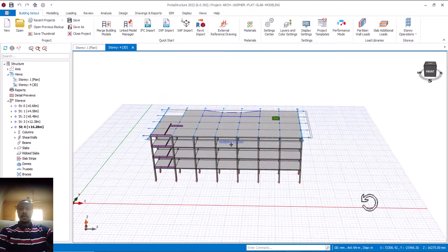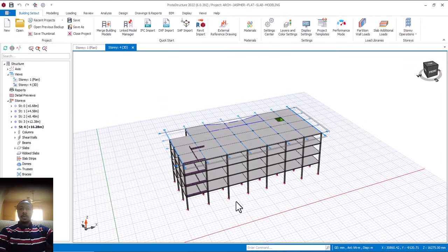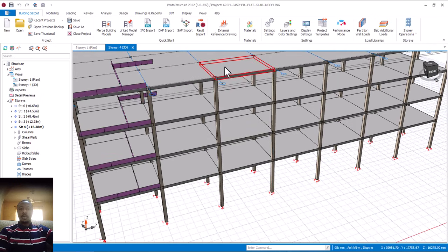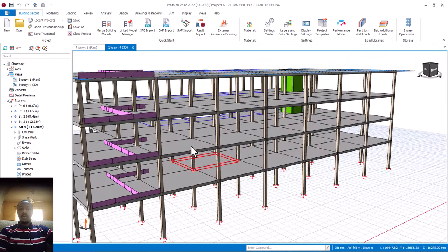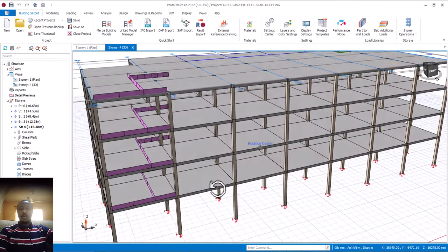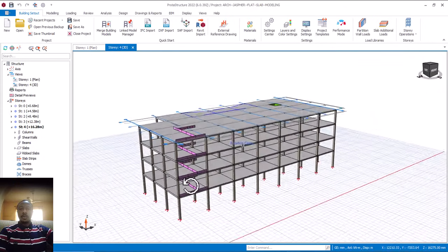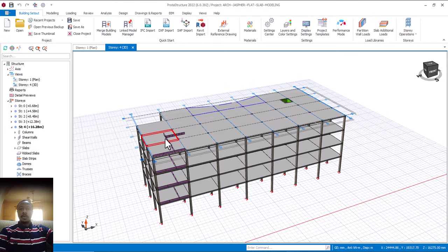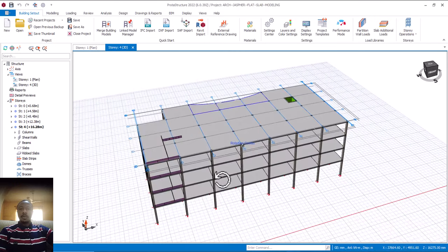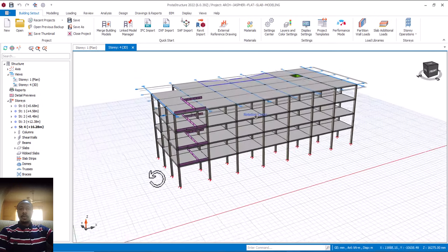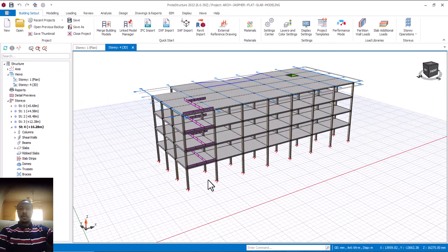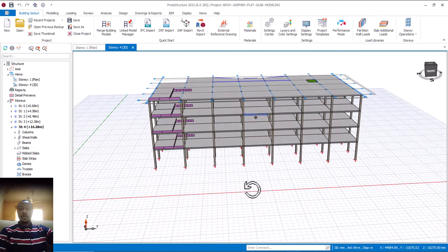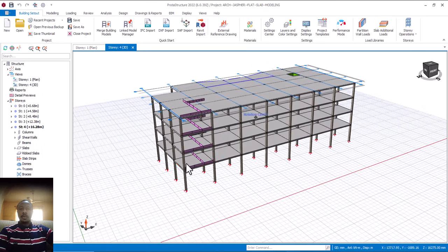So this is how you go about your flat slab, and I've explained that in flat slab, your structure must be typical. Your column from the ground floor, as you can see this one, from ground like this all through. Is that okay? We have not seen a place where I'm changing my column, isn't it? That's part of the principle of flat slab. So you must know what you are doing on how to achieve it. And you can see the area here is about 40 something square meters. Is that okay? Which is also within the principles and rules. So that is unlike the slab with beam, where the area of your slab is around 30 square meters or less than 30 square meters. But in this case, you can go beyond that. Is that okay? When it comes to a flat slab. All right.